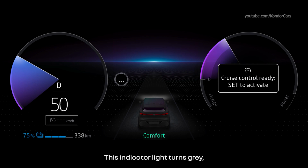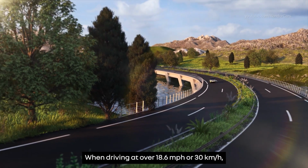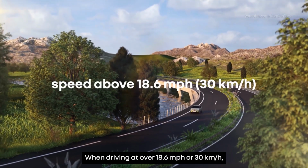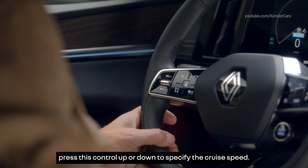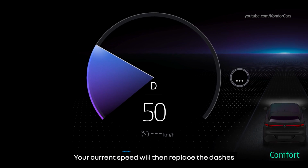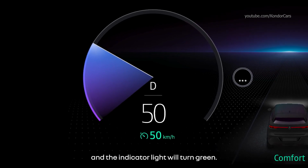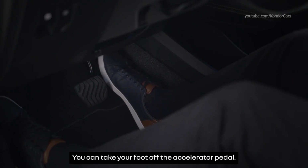This indicator light turns grey and the message "Cruise Control Ready, Set to Activate" appears on the instrument panel, along with dashes to indicate that the feature is on and ready to store a cruise speed. When driving at over 18.6 miles per hour or 30 kilometers per hour, press this control up or down to specify the cruise speed. Your current speed will then replace the dashes and the indicator light will turn green. You can take your foot off the accelerator pedal.